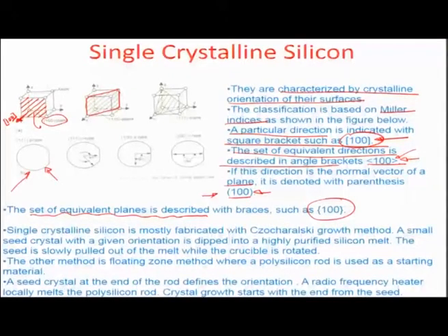Whenever wafers are cut or diced, there is a standard norm followed by the industry, which is a flat made in the primary direction. For example, this 111 p type is indicated by this flat, which means this is a plane containing all the 111 planes, and the direction 111 is exactly perpendicular to this particular plane. So, there is an international way to depict all these different aspects in a wafer as it comes handy from the foundry to the fab or the lab.